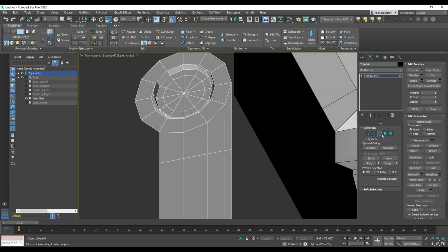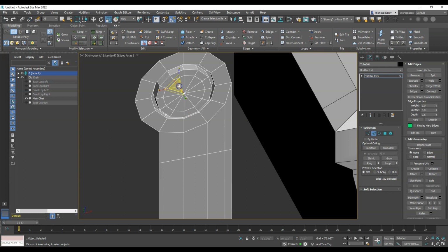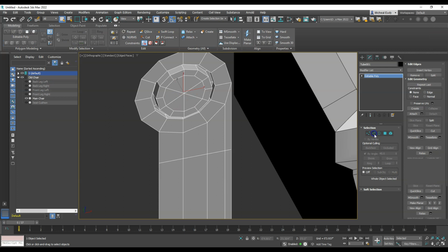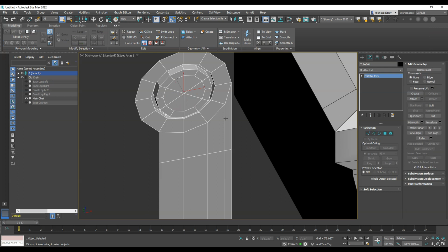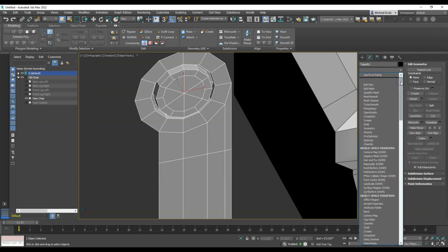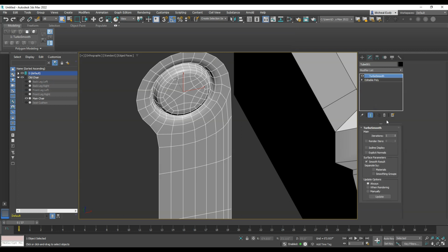Okay, so that's going to give me tris in the center in there, and so I'm going to remove every other one of these. I want to leave the ones at the top and bottom, and then I can just remove those, and now those will be quads, and that can be subdivided well. So let's put a...